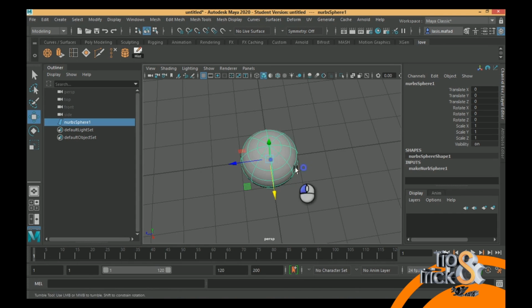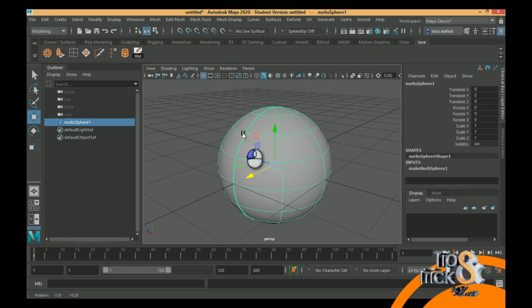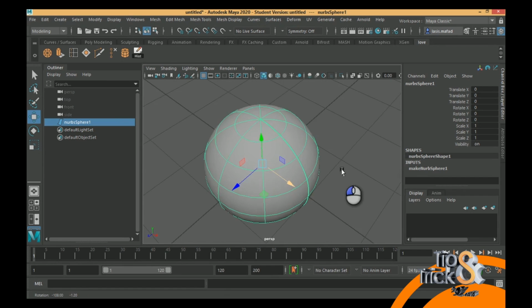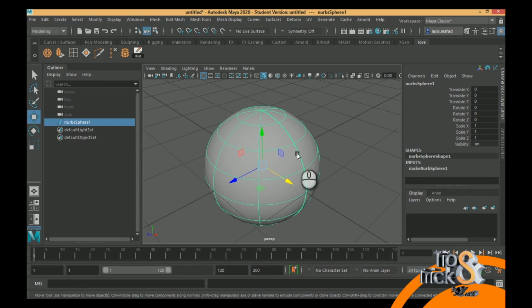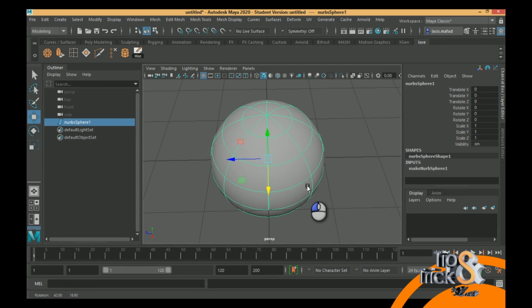you will notice when you select an object, in one area of a NURBS surface, there is this thick line. So this thick line is where the ends of the surface object meets. So it means the object is not closed. Okay.